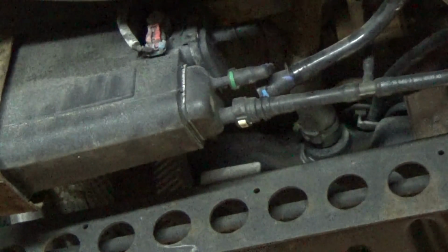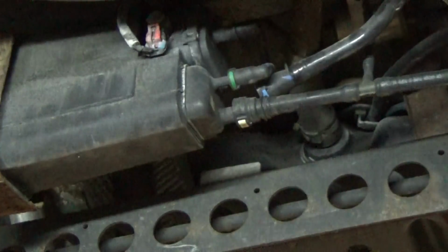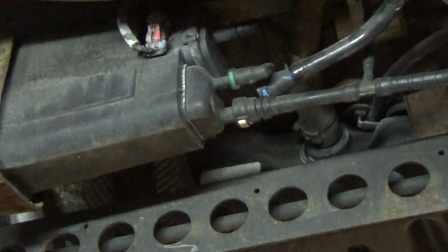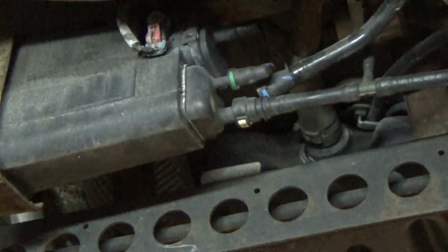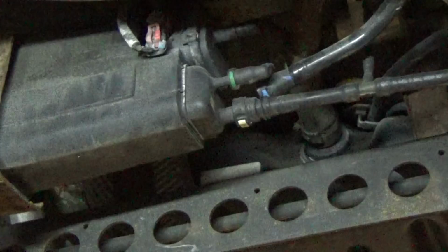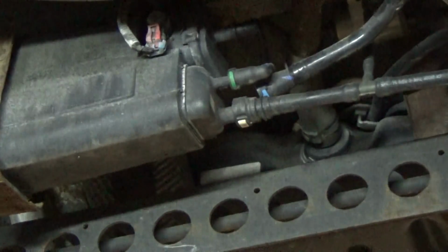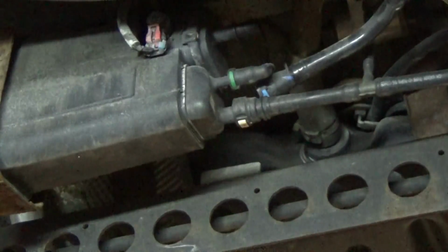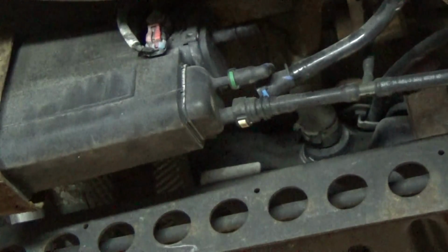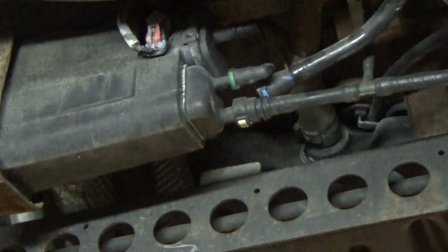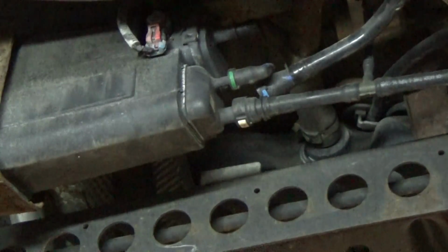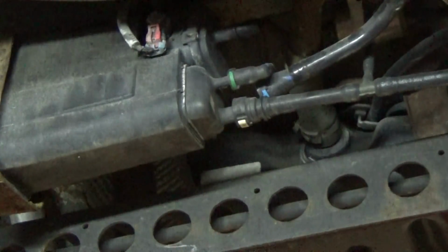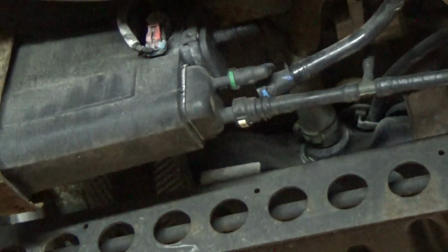For this next test, I'm simply going to turn on the purge valve and get it to start pulling a vacuum, which right now, even with the hose removed from the canister and the vent valve turned off, our fuel tank pressure sensor is reporting 4.5 millimeter mercury of vacuum in the tank. We've got a 14% duty cycle, so I don't have to do anything but reach up here and block off the vent hose, and let's see what it does.